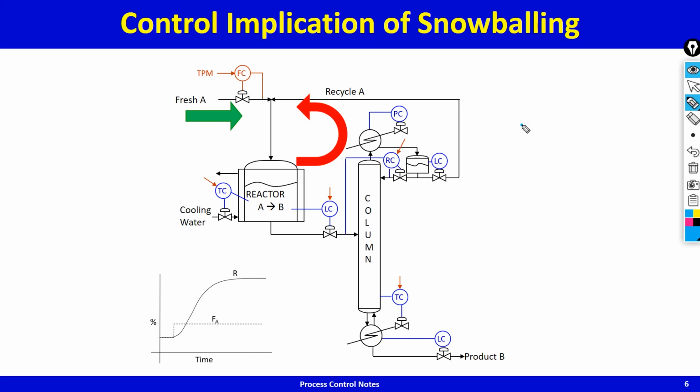He will not want to go towards the maximum because that maximum can shift and you can have overfeeding induced instability, and so he will always be operating reasonably far away from the maximum possible, and therefore you have what you call large throughput derating, as I spoke in the last lecture. So the recycle loop or recycle flow will show large swings, and therefore you get large throughput derating.